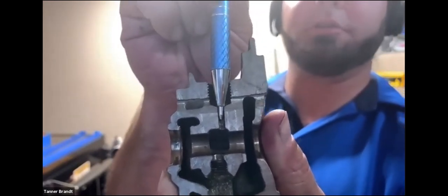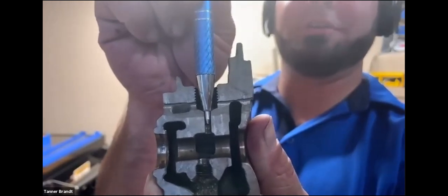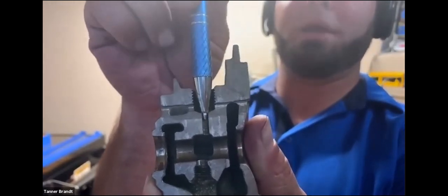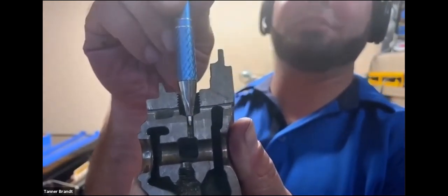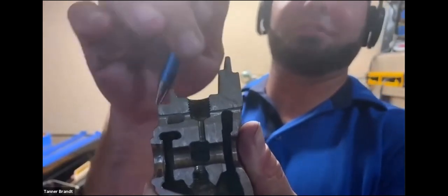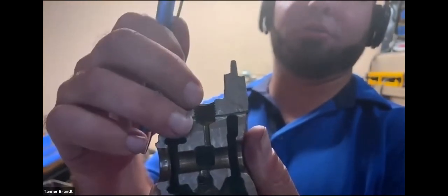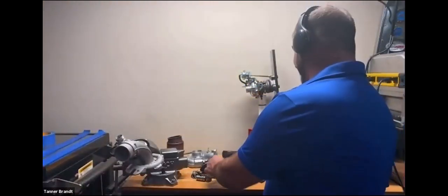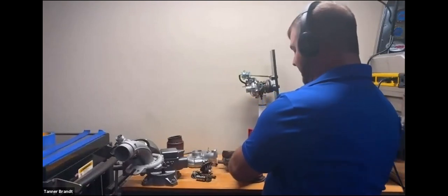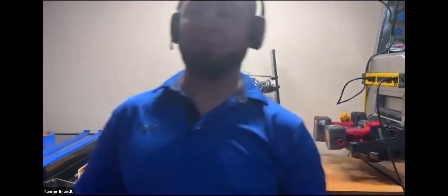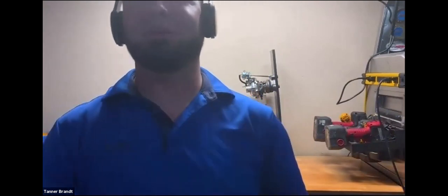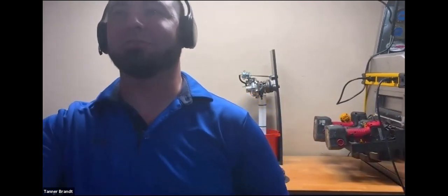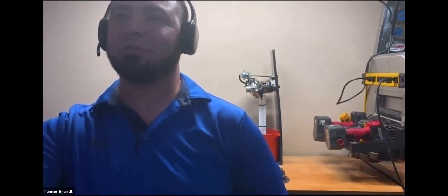That's a really, really small gallery, and poor maintenance is going to be a problem, because that oil gallery is going to get clogged. And once that's clogged, no oil is going to get to the bushings. That's a huge problem. So if there's one takeaway from the class, it's to remember the bearing housing and how it works.